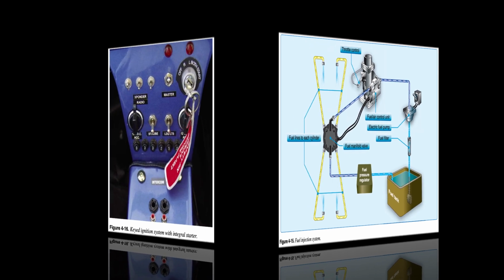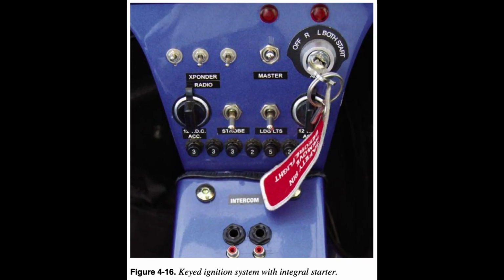Ignition system. The typical ignition system on WSC aircraft provides the spark that ignites the fuel/air mixture in the cylinders and is made up of magneto/generators, control boxes, spark plugs, high-voltage leads, and the ignition switch. For most LSA engines designed specifically for aircraft, a magneto/generator uses a permanent magnet to generate an electric current independent of the aircraft's electrical system, which might include a battery.